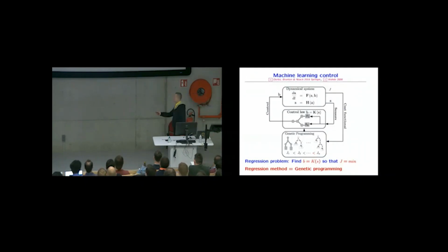So how do we go about the control laws? Well, we have our dynamical system, state, actuation. There's a fast loop. In an experiment, we may be able to respond in 1 millisecond. We measure something and we immediately actuate. And then in 5 seconds, typically in a wind tunnel, we can determine if the controller is good or not, if the drag is increased or decreased. So we have the cost and we feed it back to our machine learning box.